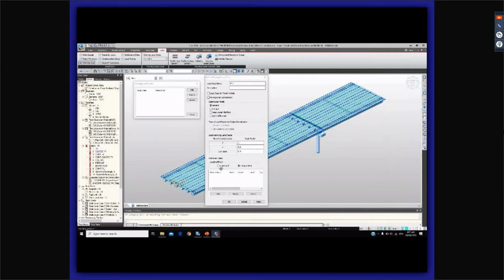There are two loading effects: combined and independent. First, if you choose independent, it will apply the load first before it gets the result. But if you choose combined, it will first combine the loads together and then give you the result based on that combined force. You could use combine and add. So first for the M1600, we have four lanes maximum, and click on OK. Then we do the same with the stationary moving loads. Then click on OK.